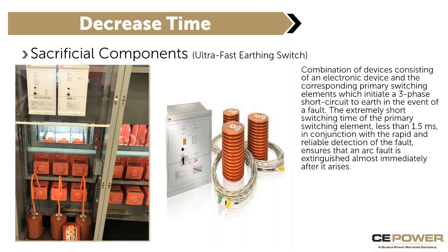So on the left-hand side of the picture, we're showing this application. I believe that's a 15 kV load break switch. So essentially what you're doing is you're creating a bolted fault in a controlled environment. And we've had situations with customers where we're going from, call it 75, 100 cals down to a class 1 type or a level 1 type hazard. So obviously PPE requirements are decreased dramatically, and it creates a much safer work environment, as well as reducing equipment hazard.